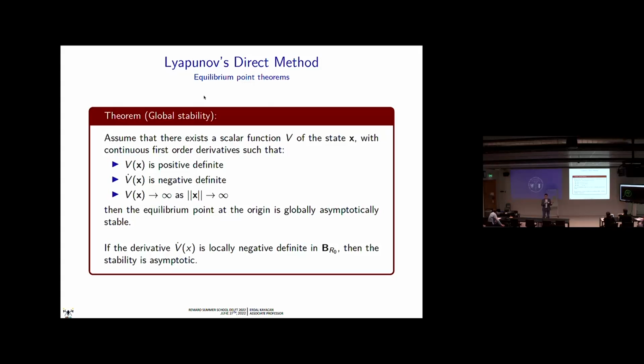If it is smaller, I can say it's asymptotic stability. So I have made comments, right? Locally Lyapunov sense of stable, locally asymptotically stable, globally Lyapunov sense of stable, globally asymptotic stability. And all of them have some similar conditions, but I think these conditions are somehow intuitive. After some time you get used to these conditions.